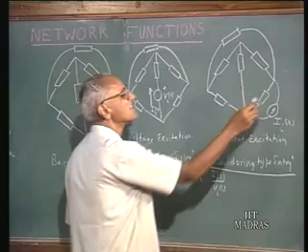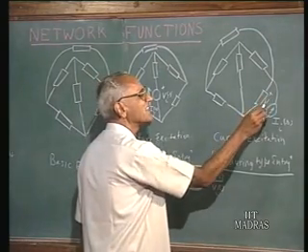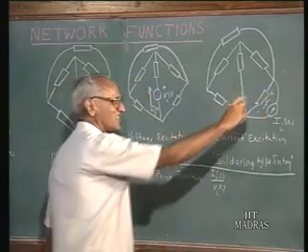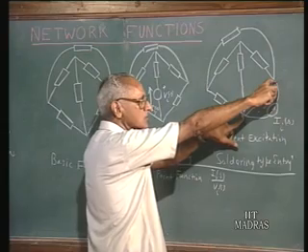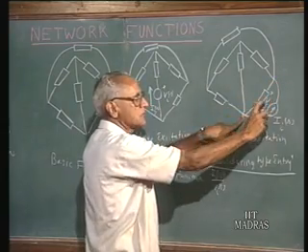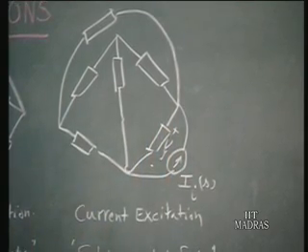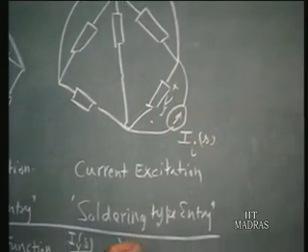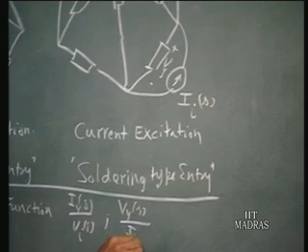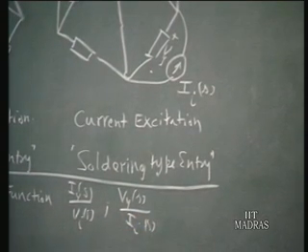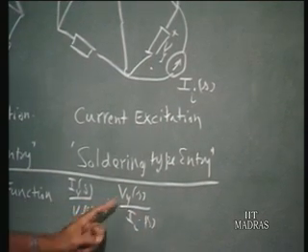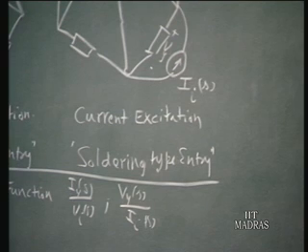In this case it happens to be a driving point admittance. In this case, suppose I have this Vy, so I am measuring the voltage across this node, the Laplace transform of the voltage, that is what is meant by Vy, and the ratio of that to Ii(s), so Vy(s) over Ii(s), this is a driving point function. In this case this happens to be a driving point impedance function.